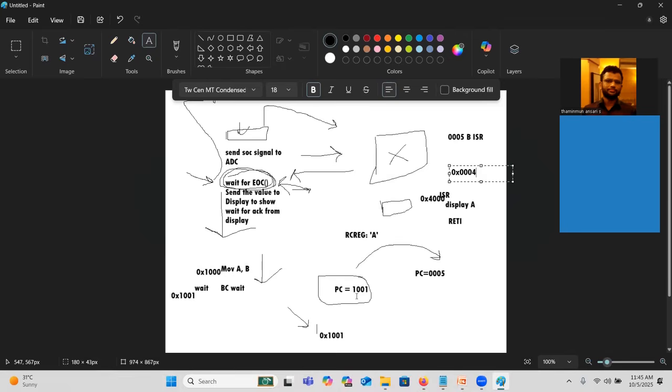Some sets of microcontrollers have an interrupt vector table. For each interrupt, they have a dedicated program memory address. Whatever instruction you have at that particular address will be executed when that particular interrupt happens. That is very straightforward and easy. In some microcontrollers, for any interrupt that happens, they will come to a single memory address only.